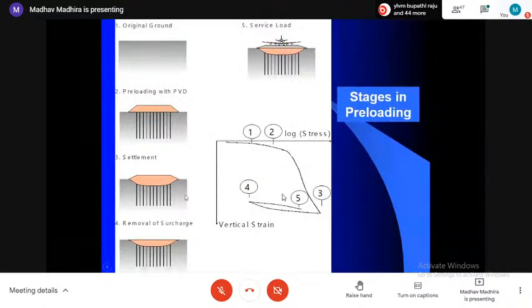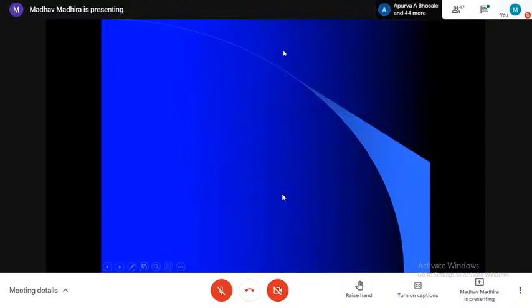Say there is one particular airport you want to construct. For example, this is one of those at Incheon. On soft clay, you provide an embankment with a drainage layer, install the drains, the settlement occurs, and then you remove the surcharge load, which is above the ground. Quite a bit of settlement can take place, maybe on the order of 1 meter, 1.2 meters. Then you construct your airport on top.